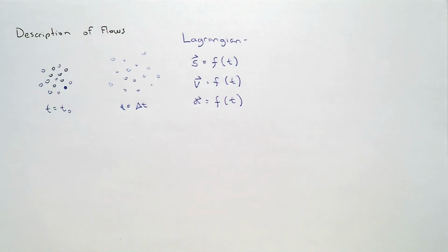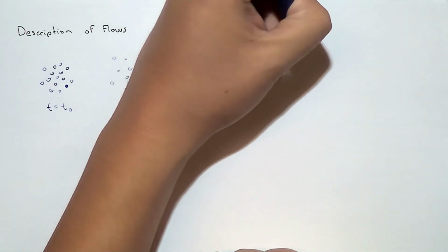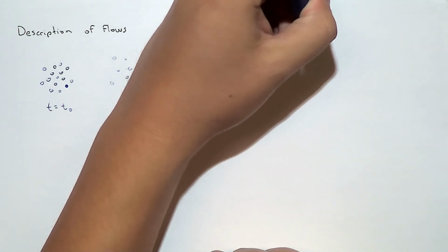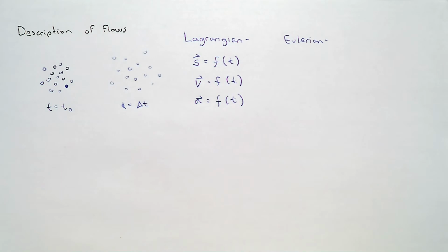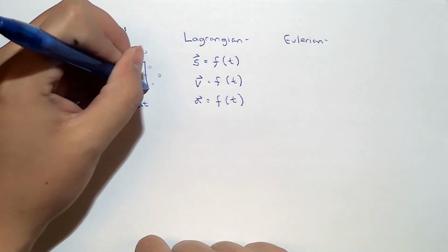So if we cannot look at fluids from a Lagrangian perspective, then the next perspective I'd like to look at is called the Eulerian approach. The Eulerian approach was named after Mr. Euler. And if you took calculus, you probably heard that name before, Euler. You probably heard Lagrange before as well. But Euler, essentially a genius in mathematics and fluids, came up with an approach where instead of studying a particle, we study a finite control volume.